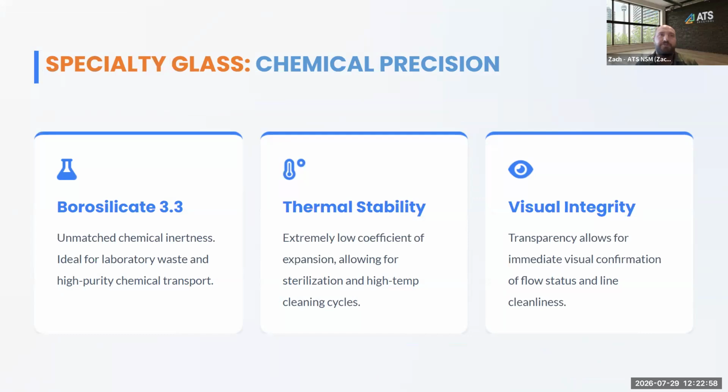We also spent a couple of different sessions talking about chemical waste applications. Everyone showed their pH tables and talked about the ranges that each fits. One of the key elements for chemical drainage, where you have, say, an ultra low pH, is that you do need to neutralize it before passing it on to the city. There's a number of different materials that can be used for that, and each material is tied to the type of chemicals that are passing through.